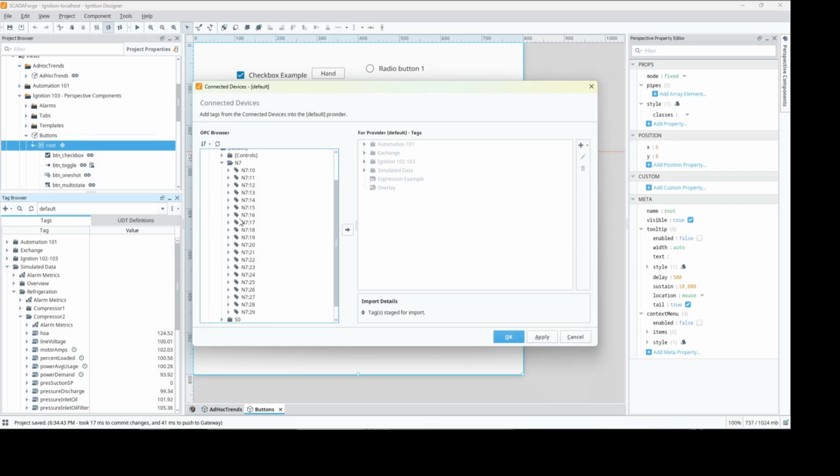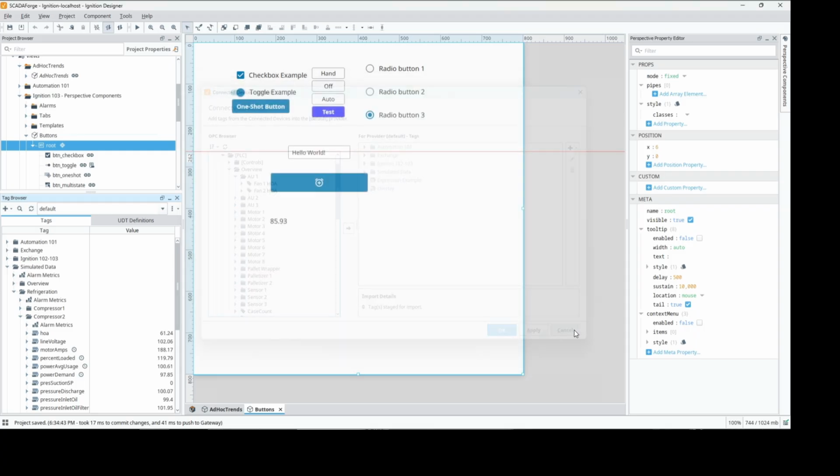This doesn't give us a useful name. Like, these could be anything. It just gives us an address in the PLC. So we would need to know either from comments in the PLC program or a drawing or something, what these actually mean. But this allows us to have a user readable tag structure.